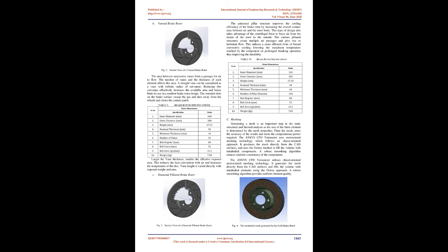Many other materials like ceramic and carbon composites are used in high-performance vehicles. These materials can withstand high temperatures and have great strength properties. Cost analysis of the disc brake rotor is to be done before finalizing design or material. The costliest material is the TiC reinforced composite, TMC. Alternate to cast iron, there are relatively low-cost AMC1 and AMC2 materials suitable to use in disc brake rotor.